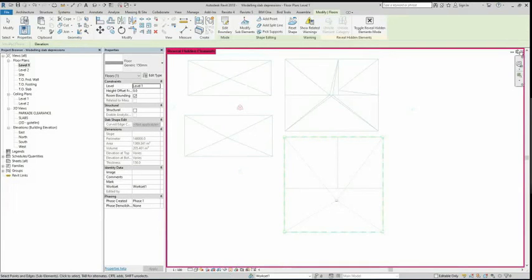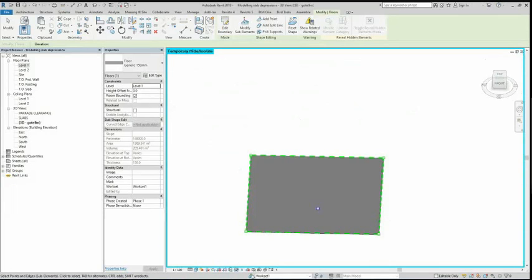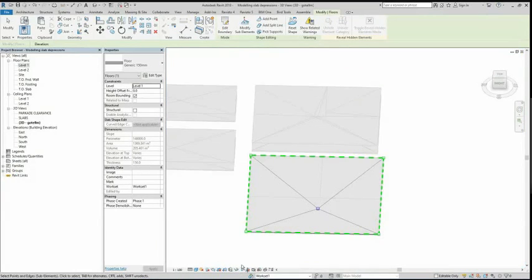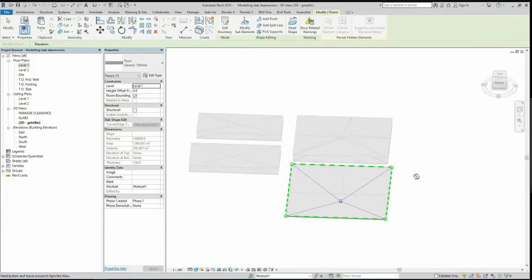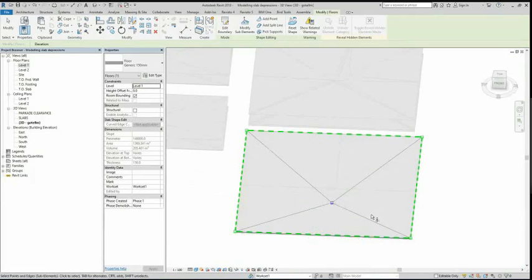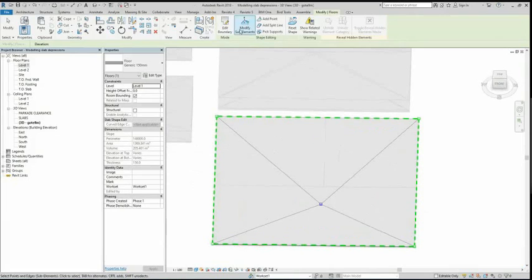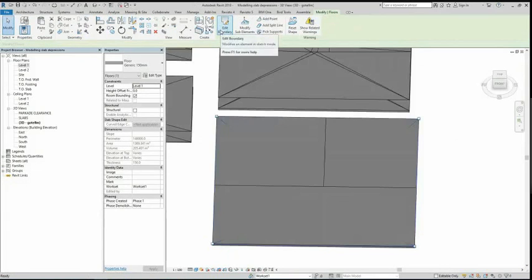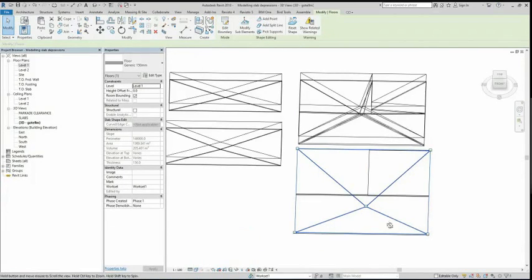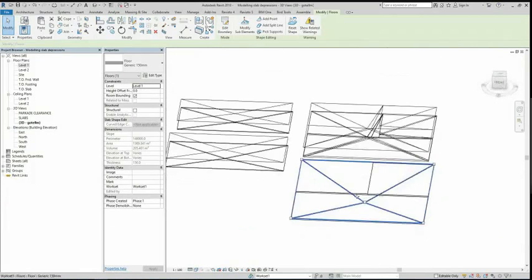So now everything is visible again, and my one single sacrificial floor element has that area drain depression. So I just want to finish those edits. And now what I want to do is turn everything, all 4 elements, into wireframe view. So now everything is in wireframe, and you'll see why I've done that in a minute here.